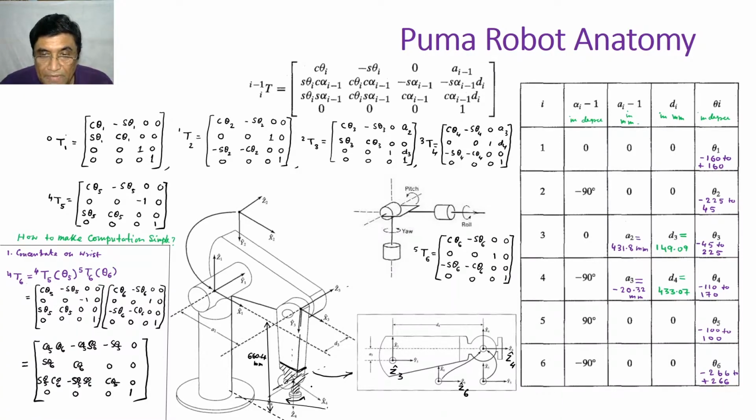And then about Z5 you rotate, this is called yaw. So this part together with this will move like this when you rotate about Z5. Is it clear? Z5, this entire lower assembly will move. And then Z6. Z6 is the angle axis. I will just show you.